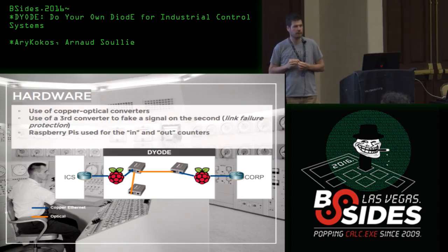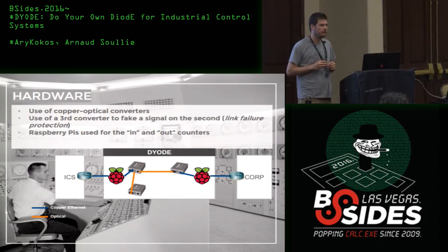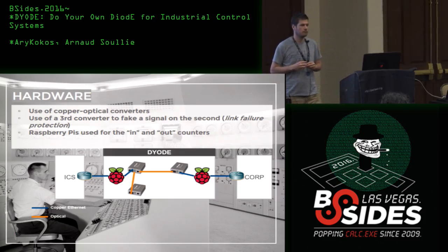Hi. Did you consider using an opto-isolator chip, which you can get for about $2, and just run serial through it? You can run those up to 10 megabits, and it wouldn't cost very much. It's a standalone chip that has both the diode and an LED built right into it. They're used pretty commonly for isolating electrical circuits from each other. I'll check it out. It might be a way to really reduce the cost. What do you call that again? It's called an opto-isolator. They're used a lot of times to divide different parts of circuits from each other electrically. Okay. And I think that would probably be right up your alley for this particular project.